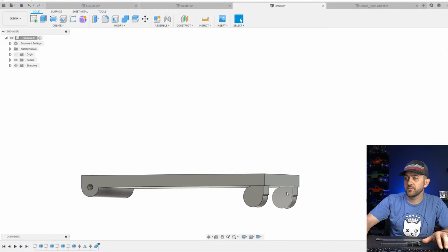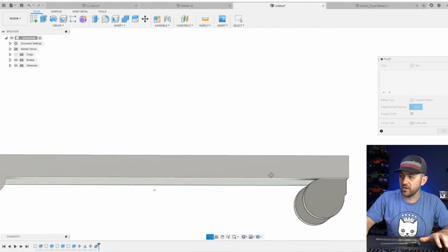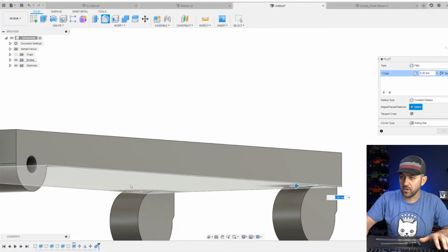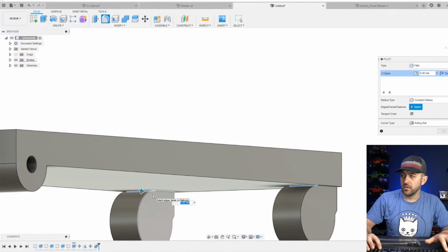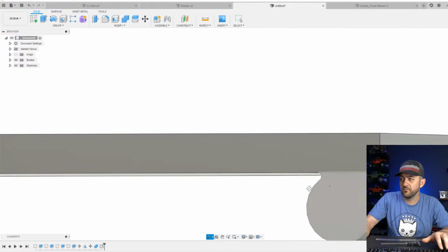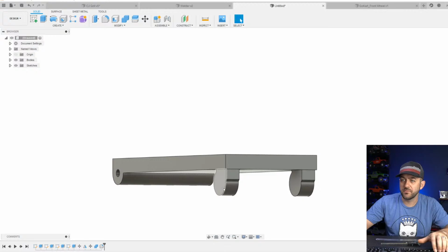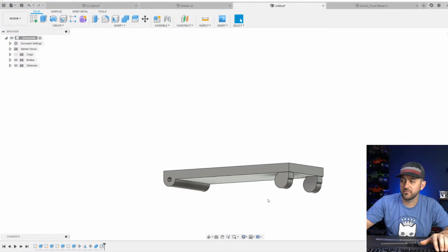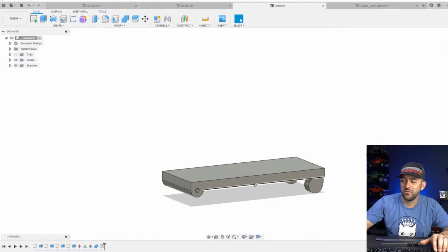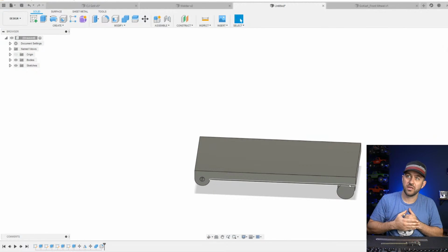Now they're combined. They're a very simple caster, but this super hard undercut edge is not great. So we're going to throw a 0.5 millimeter radius on that. It'll fill it in. It won't look too bad. It's simple. Paint these things, detail these things up with a silver Sharpie to look metallic-y, and you'll be fine. They're going to be so small and underneath of this cart anyway that I don't think it's going to be a big issue.